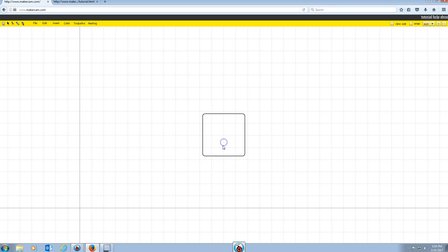We're going to click OK, and there's our rectangle. Next thing we need to do is drag it down to the corner and tuck it back next to the origin. So I'm going to select the arrow tool, select their rectangle, and move it down, and place it really carefully right there in the corner.